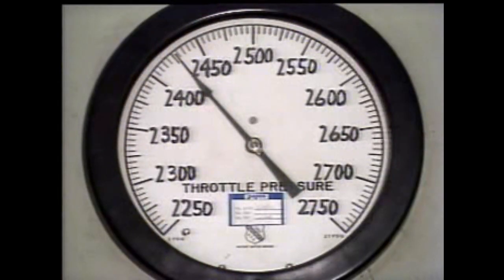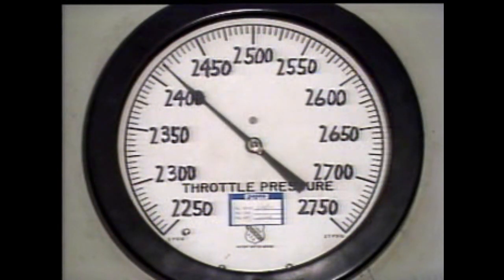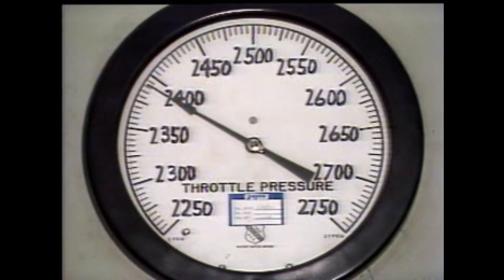Now that we've covered three general steps for dealing with a plant operation emergency, we'll apply them to a specific emergency. The loss of fire or flameout in a boiler is an emergency condition that requires immediate action. Frequently, operators can see the flame directly from the control room or on a television monitor. Some boilers have flame scanners, which are electronic devices that monitor the flame. If a flameout occurs and immediate action isn't taken, steam pressure drops. That's because the heat input to the water in the boiler has stopped, causing steam production to stop.